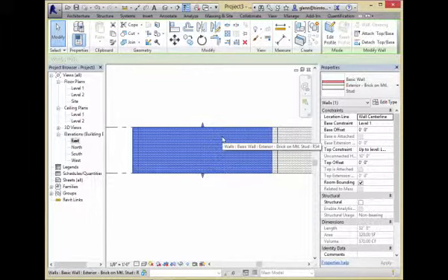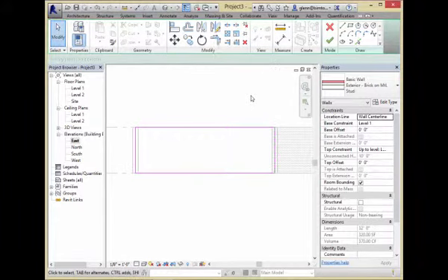One of the things that's available to us when we choose the wall in the Modify Wall tools is we can actually edit the profile. That will make the boundary accessible to us. And if you choose that, it'll expose that boundary. You'll see the pink line boundary that's defining that. So, not too bad. That's where it's actually creating a positive wall.